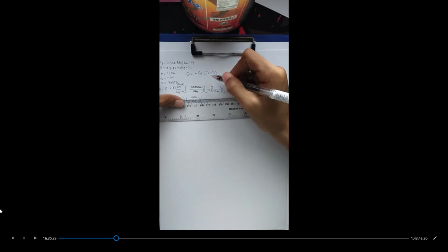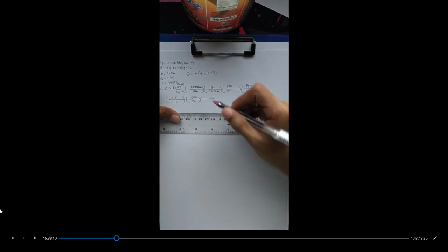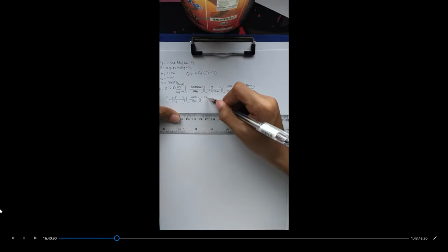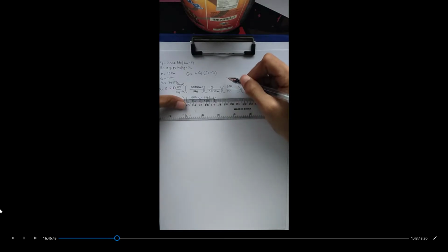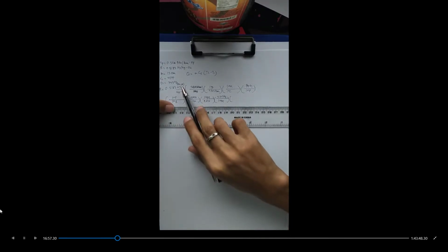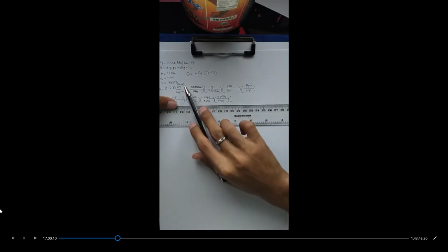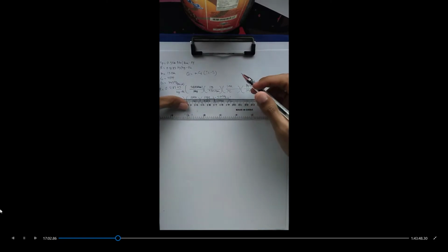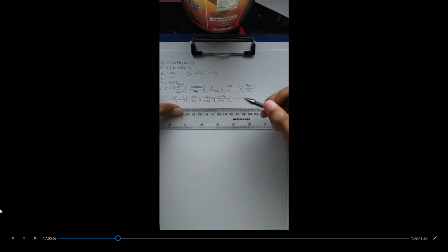And then the next thing is convert my newtons to kilogram force. So 1 kilogram force, 9.81 newtons. And kilogram force to pound force. So 2.205 pound force and 1 kilogram force here at the bottom. So I have already converted my kilonewton to pound force, and now the last thing that I would do is convert my meters to the unit of foot or feet. So in order to do so, 3.28 feet is equivalent to 1 meter.